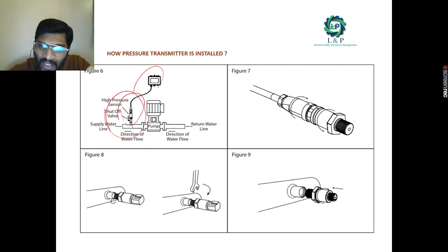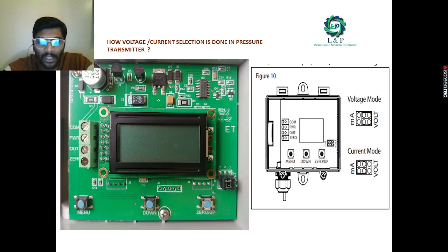and also don't install it at the pins. Okay, as you can see here, we have Allen keys to make it tight. Special provision keys and screws are there. You can use the spanners also to get them fixed inside the shut off valves.